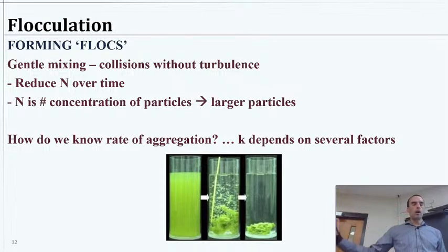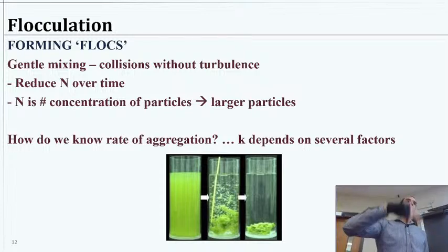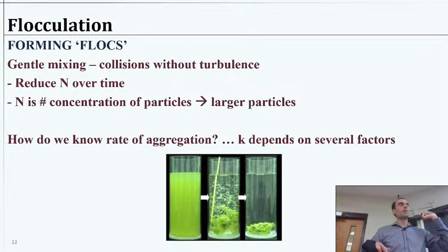So all of what we just looked at was this coagulation. That leads into us being able to flocculate our particles, to cause them to aggregate. So flocculation is a fancy term to say they're going to start sticking, right? You have one flock, which might be a few particles sticking together, or maybe we just say it's one particle. But when we flocculate, now they're starting to stick together and aggregate.